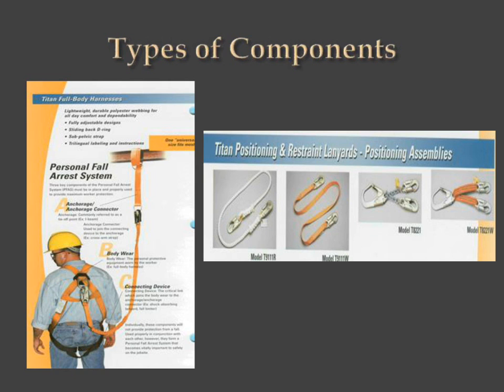The ones next to it show you that there are different kinds of lanyards. The first one is a nylon rope lanyard. The second one is a webbing lanyard. And the other two are there just to show you that you can have D-rings on the front of your belt on your harness, and those two small hooks hook into two clips on either side of that belt, and the big hook is used for positioning.